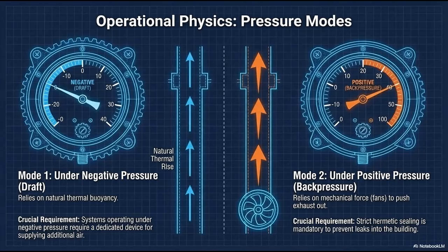Over a few harsh winters, that acid dissolves the mortar joints. It migrates horizontally through the masonry, eventually leaching through the plaster on the interior walls of your home. Causing massive structural and cosmetic decay. Exactly. Meanwhile, a modern insulated stainless steel tube behaves entirely differently.